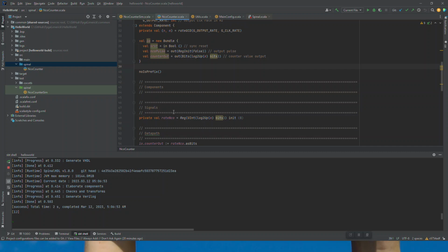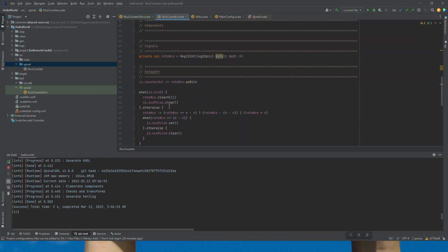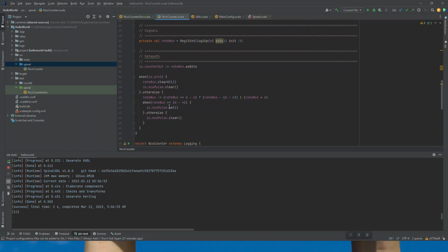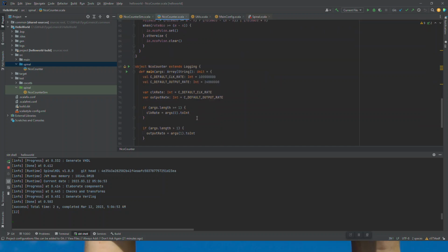So that's that for today. We just showed you the design flow of SpinalHDL, and next episode we will show you the simulation flow of SpinalHDL. Actually, we can simulate SpinalHDL itself in Verilator, or later I will also show you how to do that in Cocotb. So that will be the next few episodes for simulation. But for design flow, it's very straightforward: get the parameters, write the code, and then generate through the configuration.